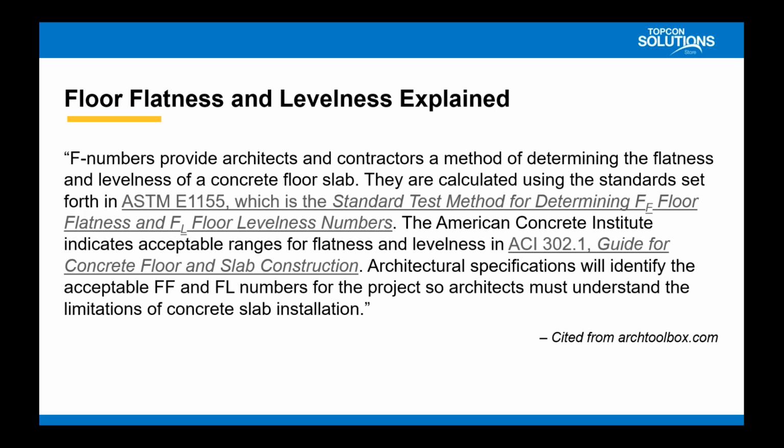Now, if we think about the concrete profiling device there, a lot of times that has to be done on a finished slab, right? So one big thing here is that when we look at that, you're already past the point where you can go back and rework the slab. Now, yes, you can call somebody back out and try to get them to adjust the high spots, or come back in and bring some concrete in for those low spots, whatever it may be. You have to get the results that you specified within tolerance, right?